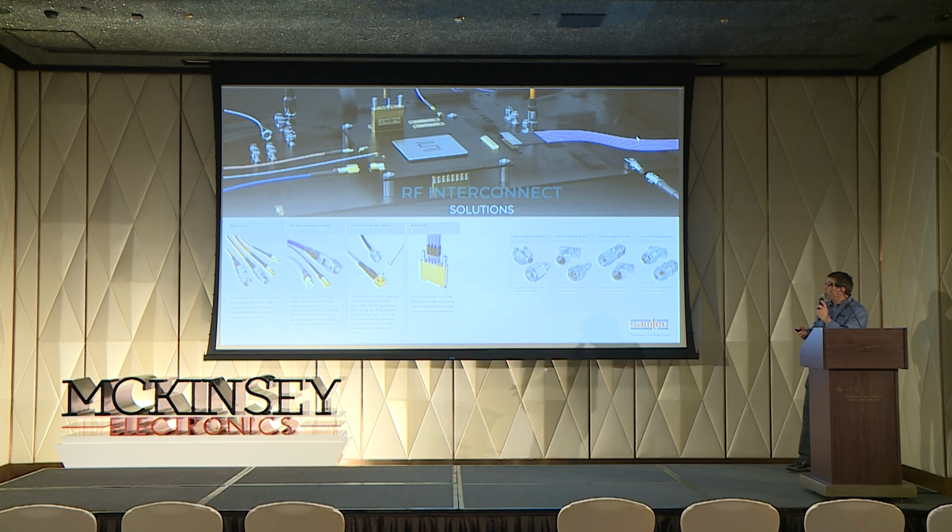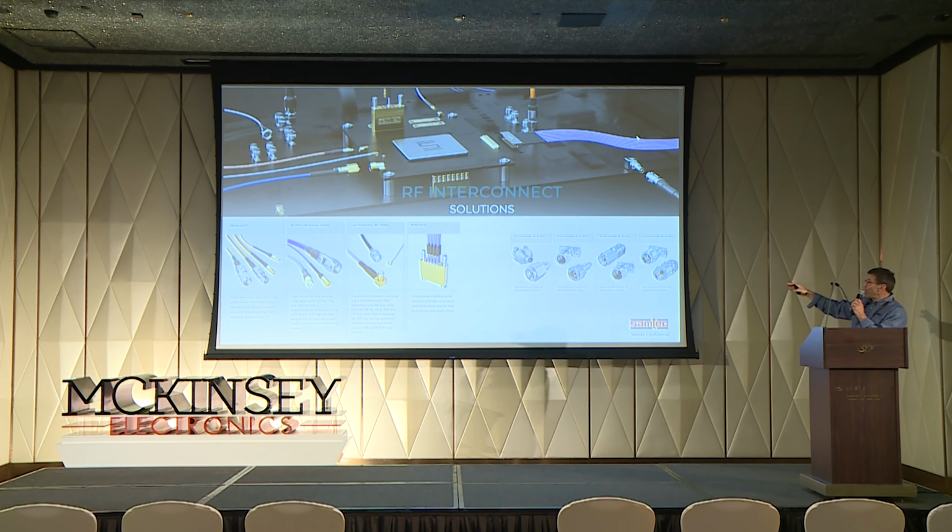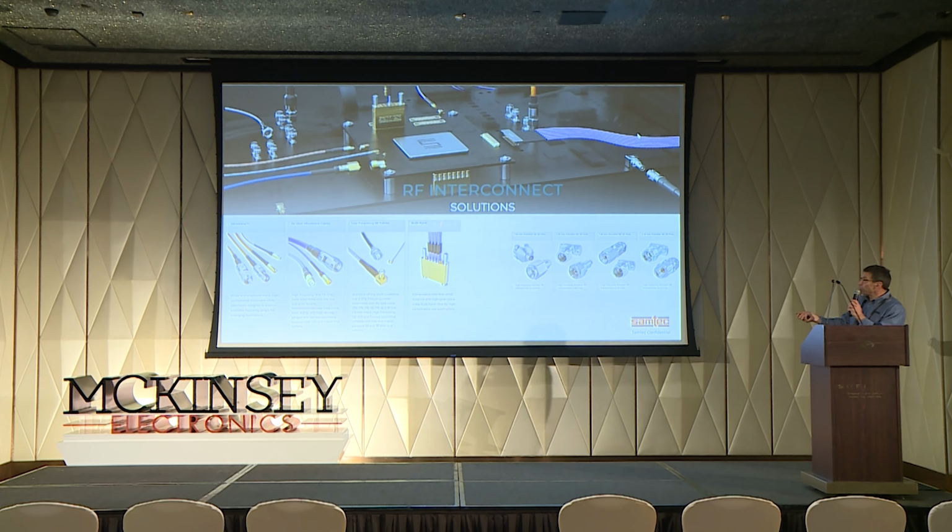Thinking of RF, we've got both cable and board sockets. We go down to 1 millimeter, 1.85, 1.35, 2.4, up to 3.5 millimeter SMAs as test points. For those, we also mate with cable assemblies. We can mix and match cable types. We've got our own orange cable now, called Nitrowave, which gets us up to 112 gig frequencies in RF. We come across to other cable types, including what we see here as Bullseye.